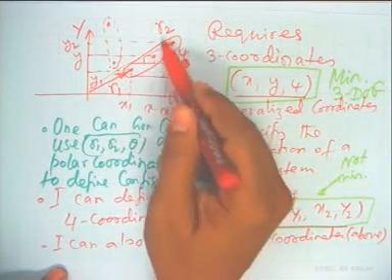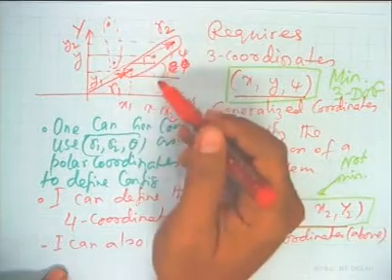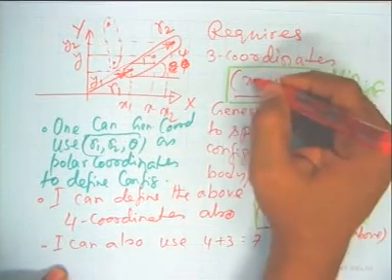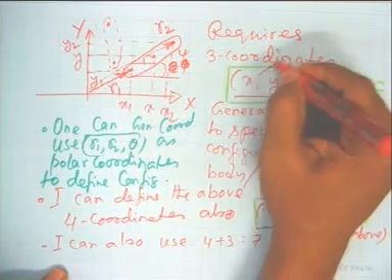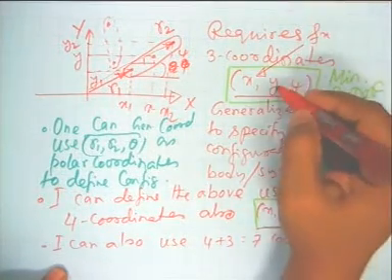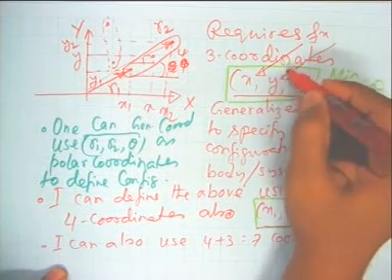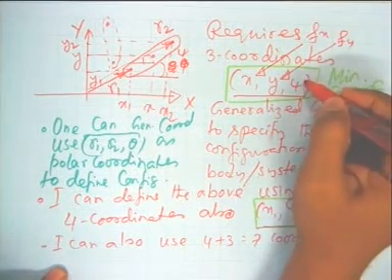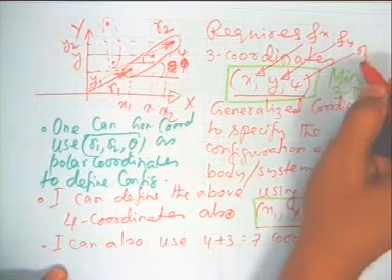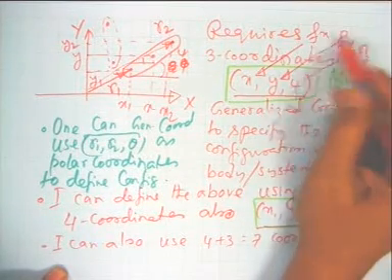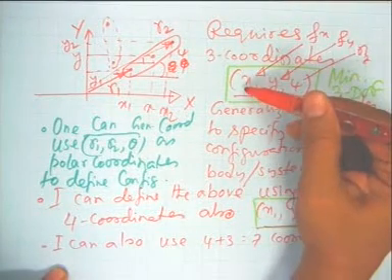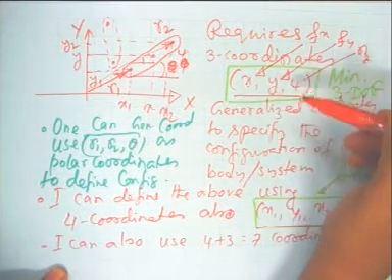To rotate this body, I need a certain torque. So, if I want to get a displacement x, who causes this displacement? This is say Fx. Who causes this displacement? Fy. Who causes this displacement? This is say moment about z. So, these three become the generalized forces corresponding to the generalized displacements x, y and psi.